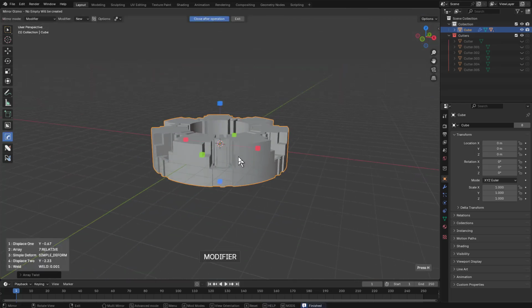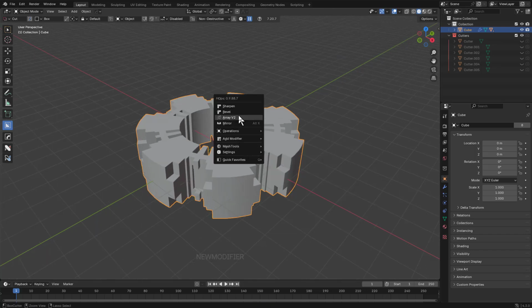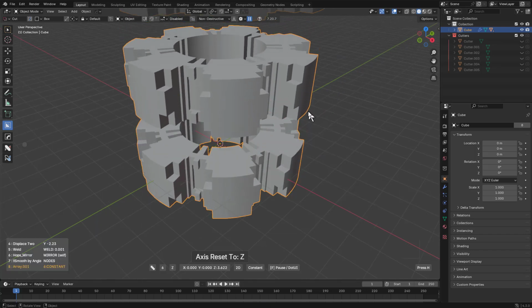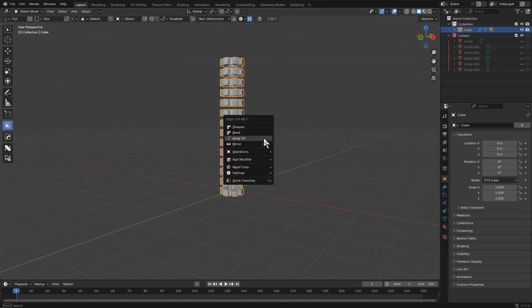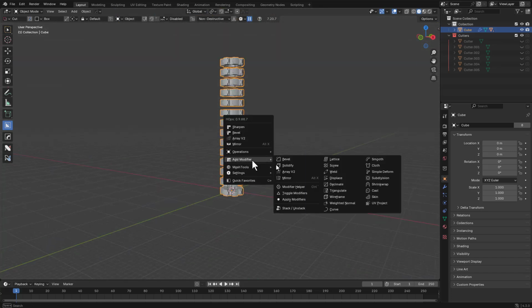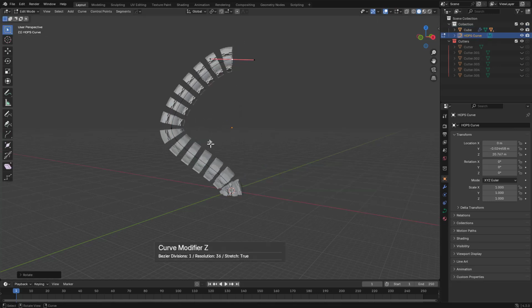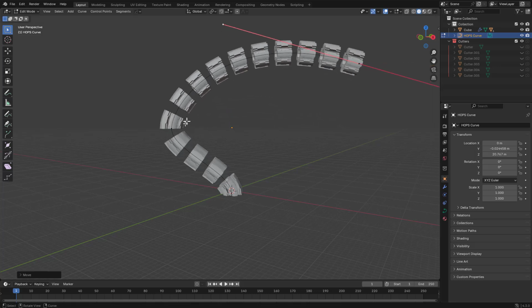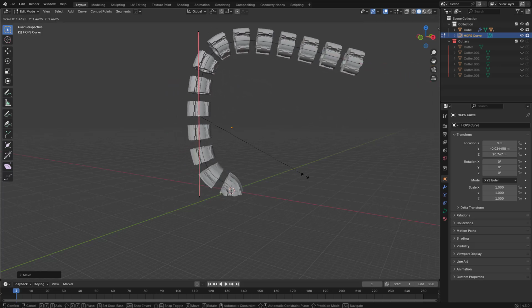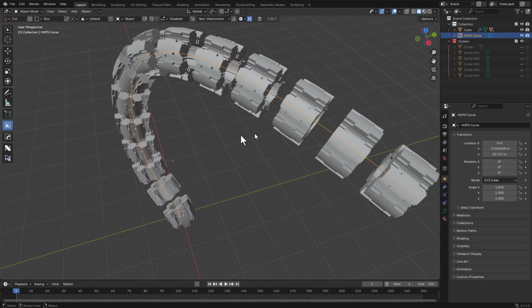Let's press Alt X. We'll press A in order to add a new mirror. We'll just mirror it below itself. I'm just going to control click array in order to add another array modifier on top of all of this, where we can just scroll this up into becoming a line. Under add modifier, we're just going to add curve, go in edit mode, and now I'm able to deform this shape no matter what. And this was just a basic cube that we took and deformed into this, but just like that, we were able to get started with hardops and Box Cutter without any issue.